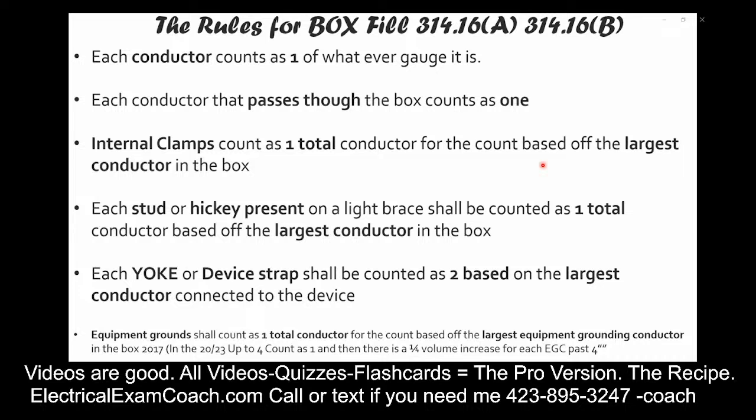It's only counted as one total based off the largest conductor in the box. Meaning it doesn't matter if you have 10 equipment grounding conductors, they all only count as one for your count total, and it's based off the largest conductor that's in the box. So if I have 10s and 12s, it's only going to count as one number 10.